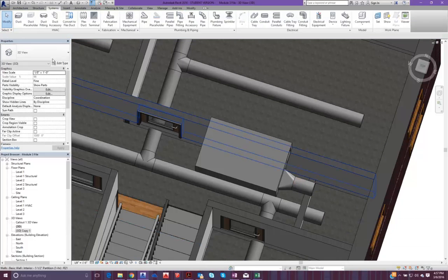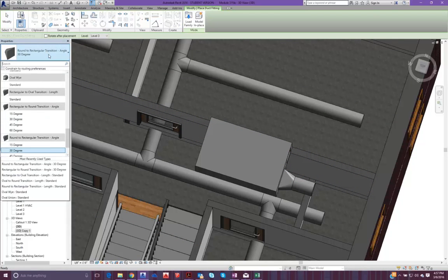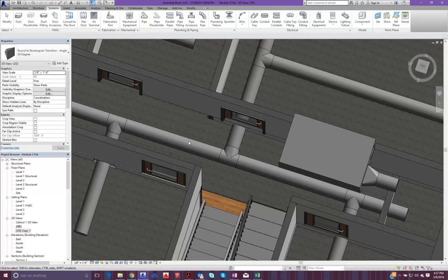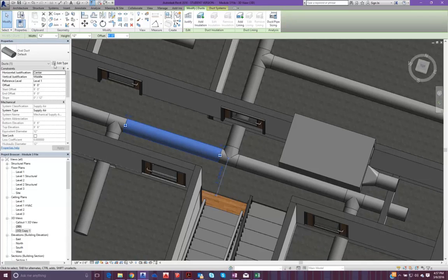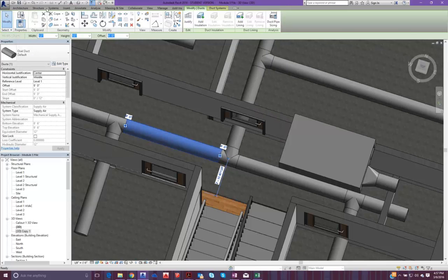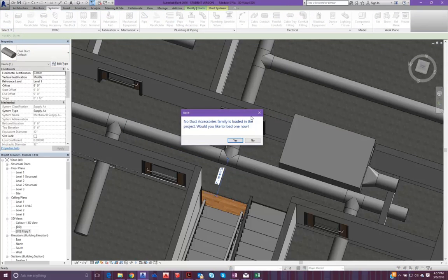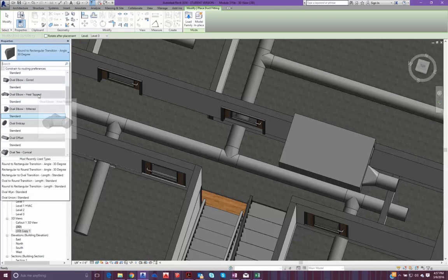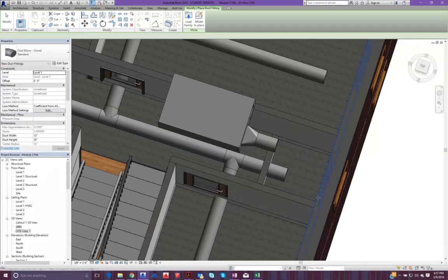So that's pretty typical. What we have to do there is go to this duct fitting, and we'll go down to, let's see what fitting we have preset for our ductwork. We can go here, we'll go to edit type, edit, and we have an oval T conical standard. We need an oval elbow board standard. So go here to systems. Let's go here and we'll go to oval elbow board standard as we have in the rest of the system. And let's go ahead and connect this.